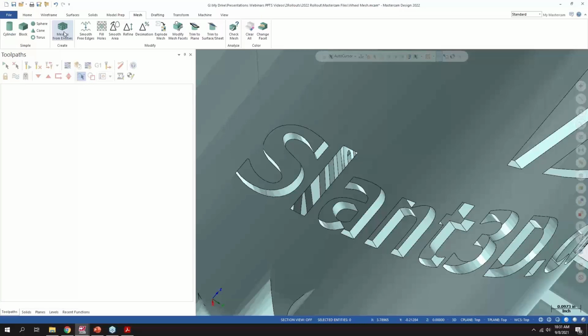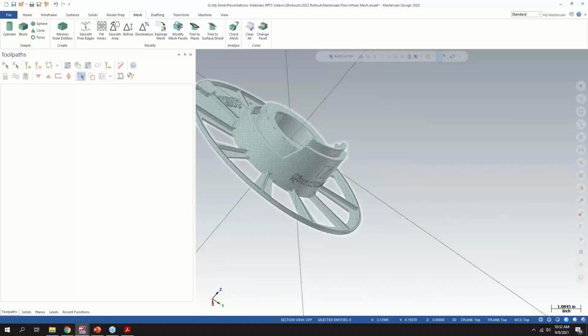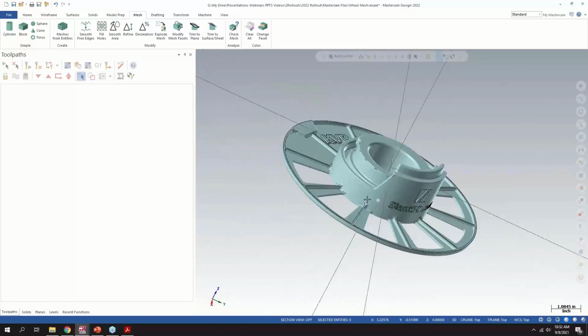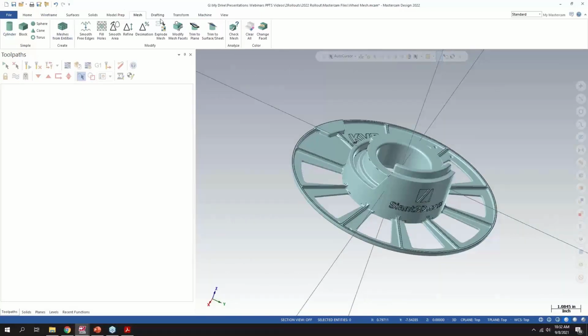So a stock model is just a mesh. So you should be able to use an STL as a reference for your stock model, and it would be almost exactly the same as if you created a stock model from scratch, because a stock model is a P mesh just in a toolpath form. I could probably do that here.